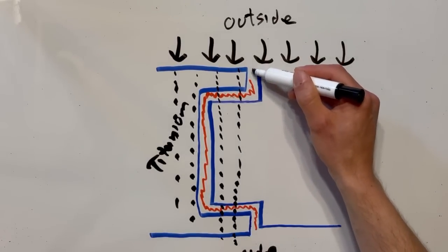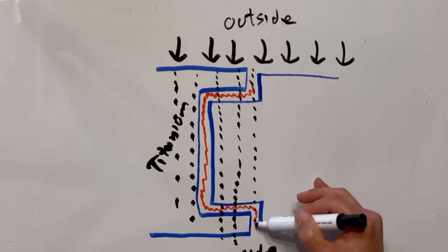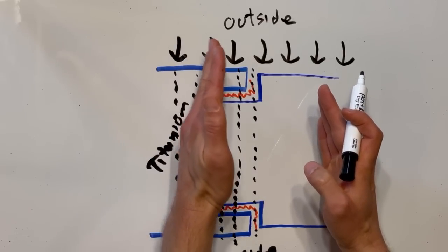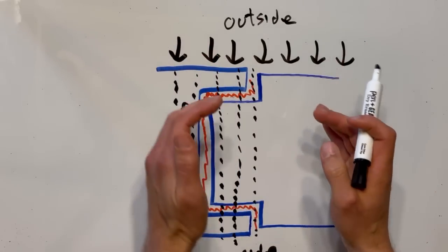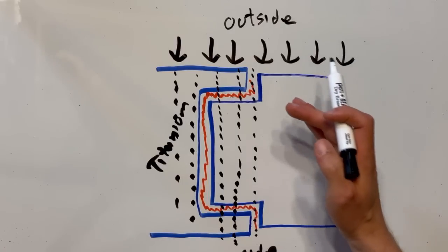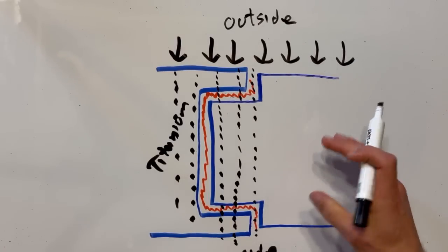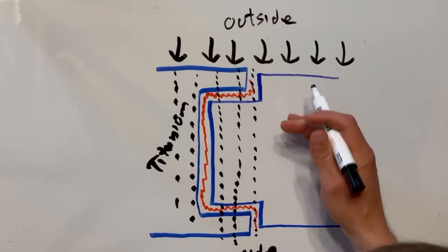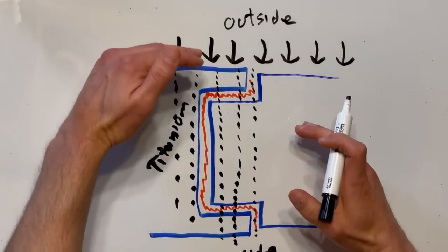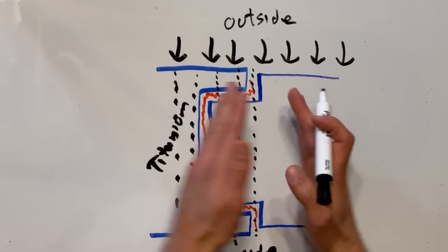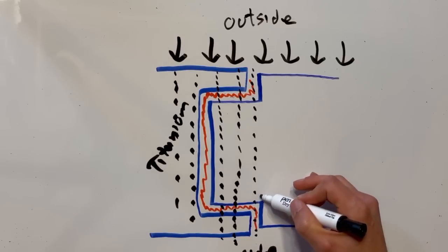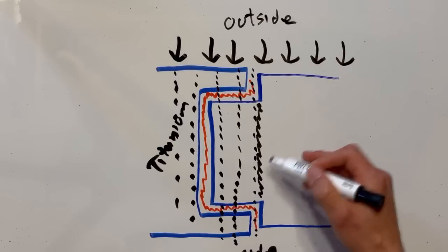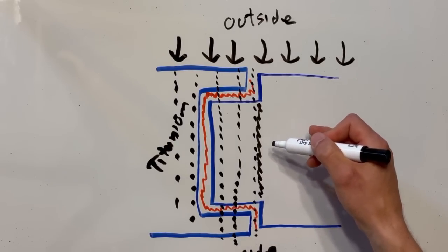But then right here at the joint, there is a very sharp transition from titanium and carbon fiber to just carbon fiber. With this reacting differently to the pressure than the carbon fiber, likely one of these is going to be compressing more than the other half of that line. So that creates a shear stress along this boundary. And the shear stress for that composite is not good.